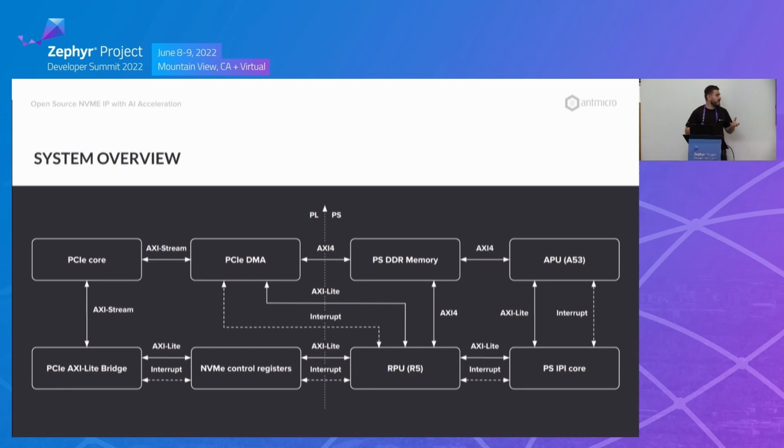So having the platform, we're able to split the system into two parts. On the left side, displayed the same way I see it here, there is an FPGA part, the part where we could implement all the logic we need, all the additional digital circuitry that we need to handle NVMe transactions. And on the right side, we have the whole SoC complex with Cortex-R5 and Cortex-A53 CPUs running some software that we want to utilize.